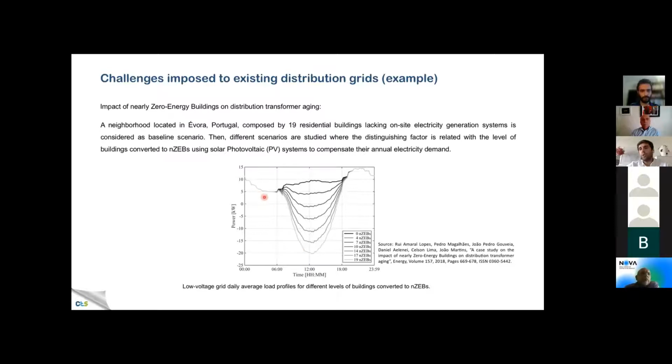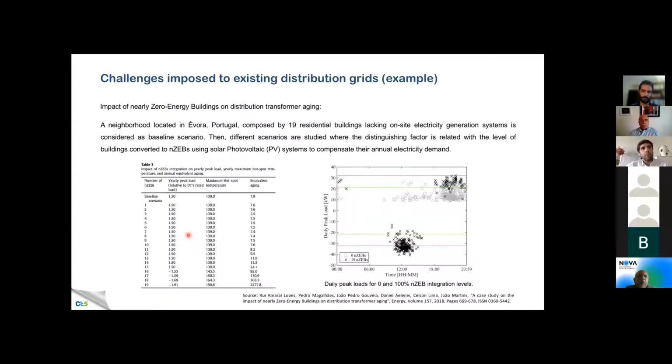So this is an example where we could transfer some energy consumption from these parts of the day, evening and morning, to periods around noon, when the coincident solar generation of these 19 buildings is higher. We could use batteries, thermal storage devices, like heat pumps, or air conditioning as well. We could cool the building during the morning or during noon to avoid cooling at evening, and so on. Several examples exist.